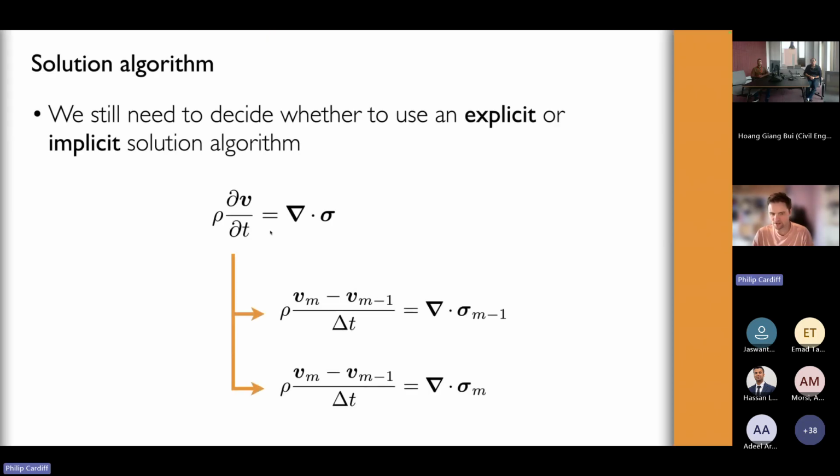Then another major choice, like in finite element or other methods, is when you solve your equations, you can solve them explicitly or implicitly. So if we do it implicitly, let's say the surface forces are written in terms of the current time unknown displacements, you have to solve some sort of linear system. So here's maybe one key difference with normal OpenFOAM or finite volume methods and finite element methods.